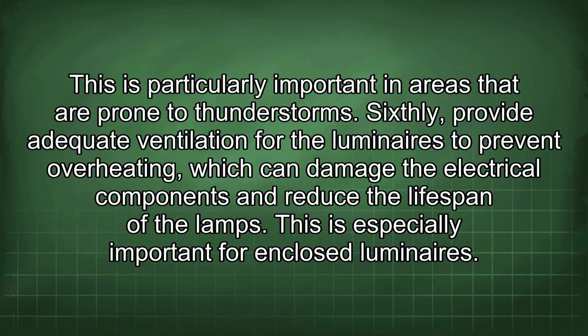Sixthly, provide adequate ventilation for the luminaires to prevent overheating, which can damage the electrical components and reduce the lifespan of the lamps.